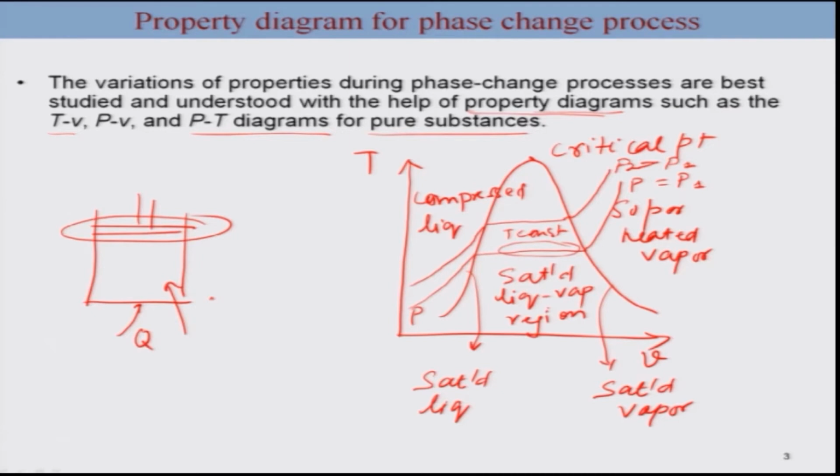Now you notice that the slope of this line, okay, is positive. So essentially del T by del V at constant P is greater than or equal to 0, right, because in the intermediate range it is 0. So here at any intermediate point, you have a system which consists of some vapor and some liquid. You can understand the same thing if you change the TV diagram to a pressure-volume diagram.